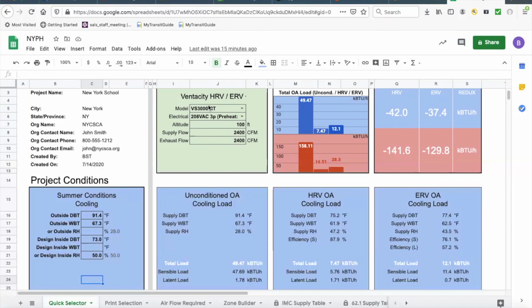And there are a couple reasons for that. One is it's at its least efficient operating at capacity, both for heat recovery rate. Obviously, if you're moving air more quickly in both directions through that heat exchanger, maximum volume in both directions, you're going to have a lower level of recovery. And your static pressure, which means your fans, are going to be using higher amounts of electricity to move that air.